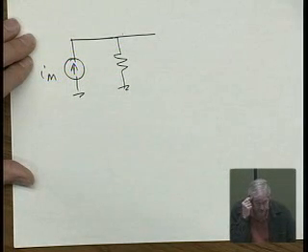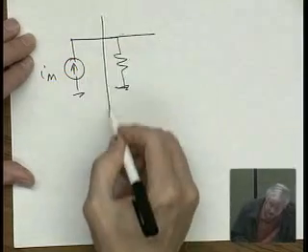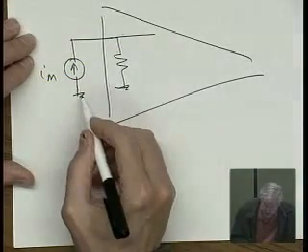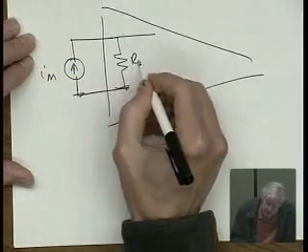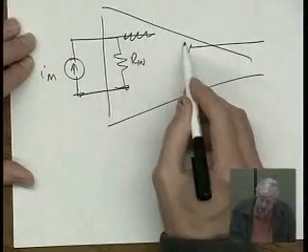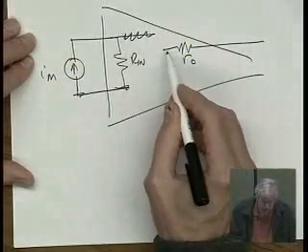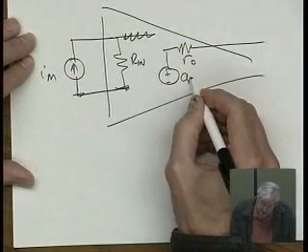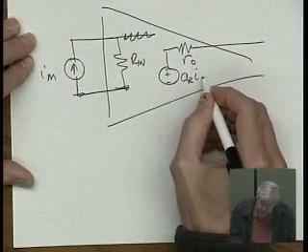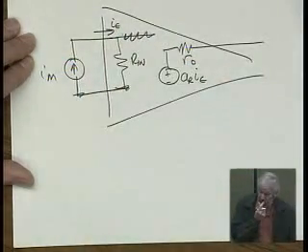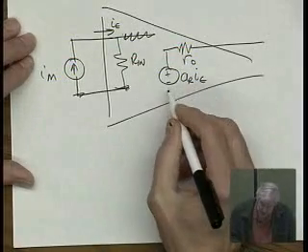Let's see here. We'll do this. Here's our basic amplifier right here, and here's the R in of the basic amplifier. Here's our R out. Here's our gain, A sub R times I error, and I error is the current going into this amplifier. And here's the output.